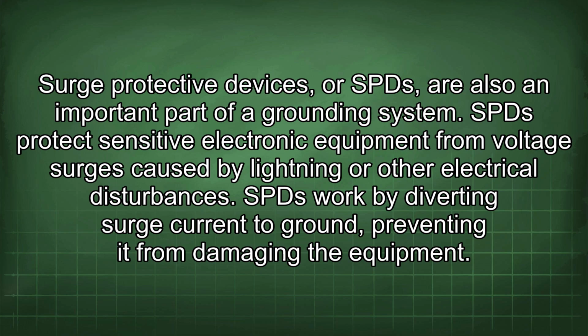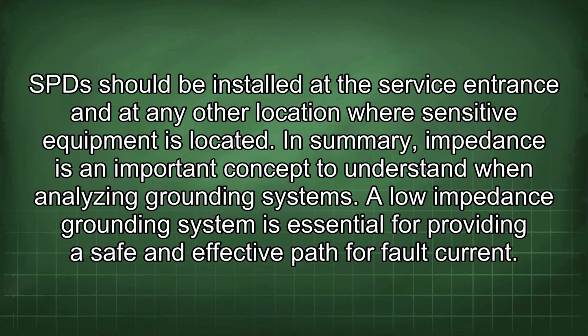SPDs protect sensitive electronic equipment from voltage surges caused by lightning or other electrical disturbances. SPDs work by diverting surge current to ground, preventing it from damaging the equipment. SPDs should be installed at the service entrance and at any other location where sensitive equipment is located.